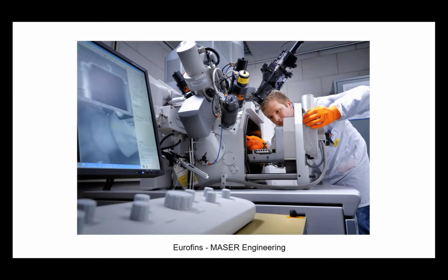These instruments are very expensive, and in contrast to the older instruments driven entirely by software, an analyst technician has to have a good idea of what this instrument does, working with a high vacuum system, a dual beam source, both electrons and gallium ion gun, and then not only capturing images, but doing circuit trace on here. And this is a beautiful instrument that with time and given training, technicians become very proficient at running.